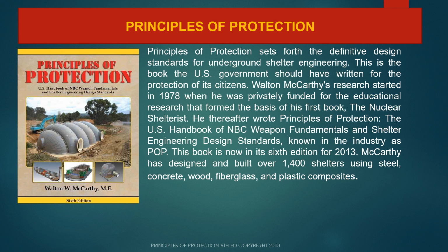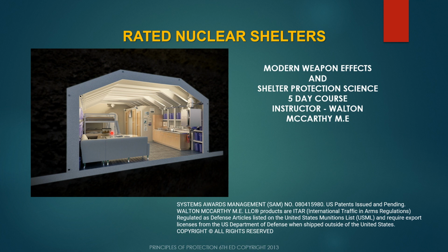Good morning, everybody. Today we're going to be reviewing, in session 3, overpressure control to prevent pressure from building up inside the shelter. Usually if you're in a shelter that is designed to be a bomb shelter, that's not a fallout shelter, but designed to be exposed to either blast wave or overpressure or ground shock, then you would be in this category requiring some type of overpressure control inside the shelter.